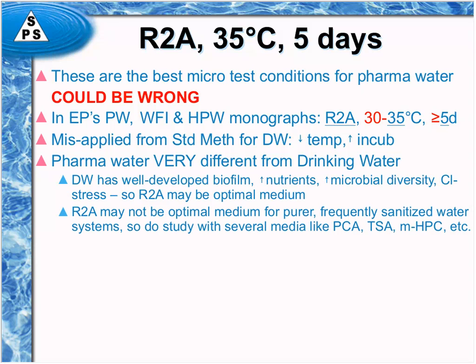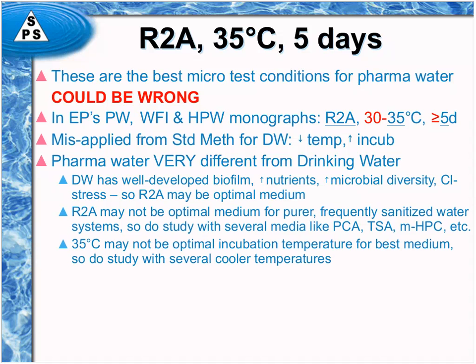However, it may not be optimal for pharmaceutical water because pharmaceutical water is pure, it's frequently sanitized, and so you really ought to do a study where you evaluate perhaps several different media, high nutrient and low nutrient media, against a variety of temperatures, because maybe 35 isn't the best temperature.